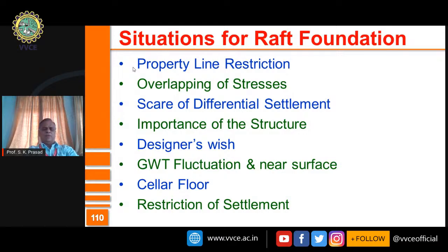Whenever groundwater table is likely to fluctuate from near the ground level to a lower level, it is preferred that we provide a raft foundation which will be solid one. If not, between the foundation, water will rise. Naturally, it's going to cause unpleasant situations under several circumstances, and many a times you don't want the groundwater to go into the foundation area.